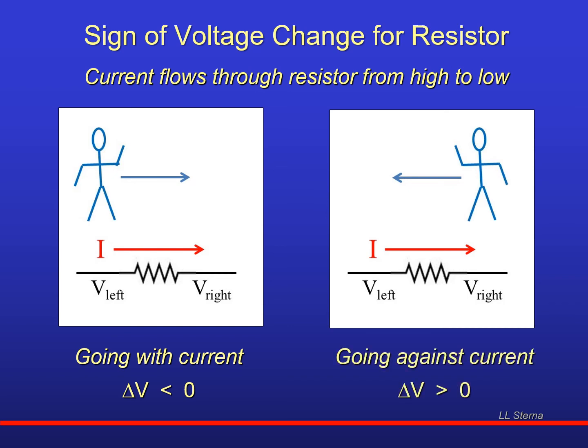Your delta V, the later minus where you started, V left minus V right, will be a positive number. Now, when we calculate these voltage changes, we'll use Ohm's law, delta V = I times R. But what we're going to find out is we have to use a positive or negative sign when we apply that law.